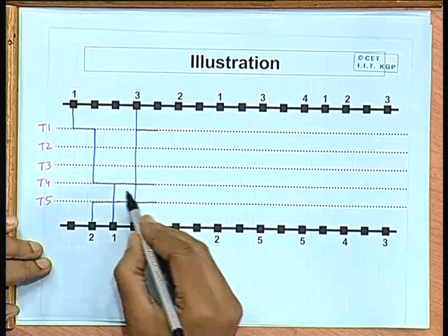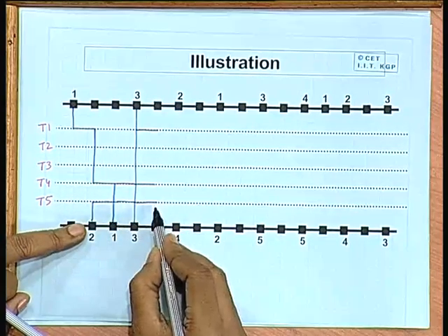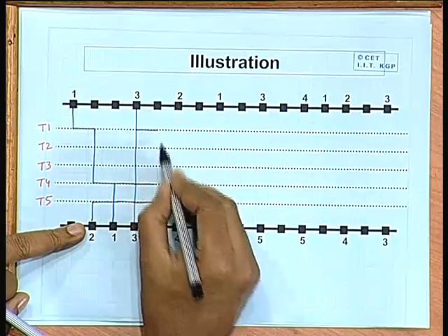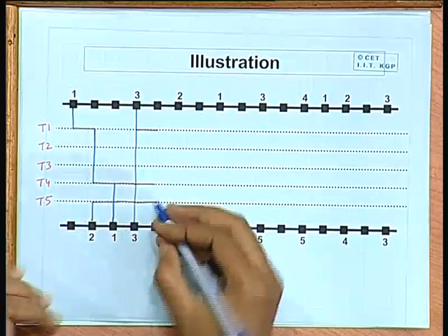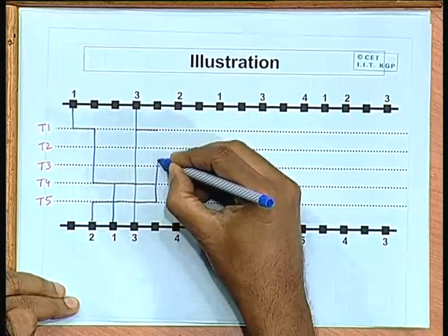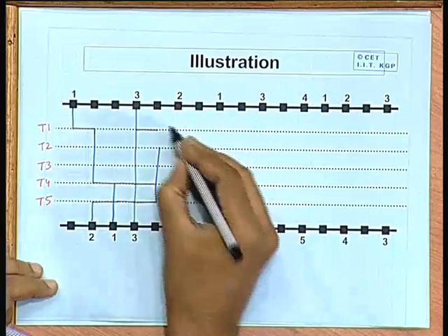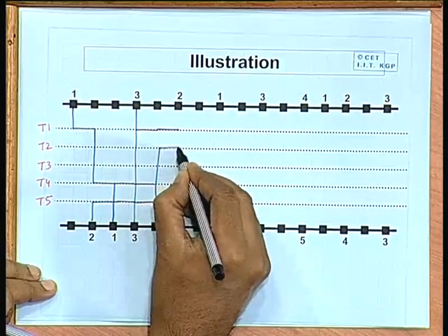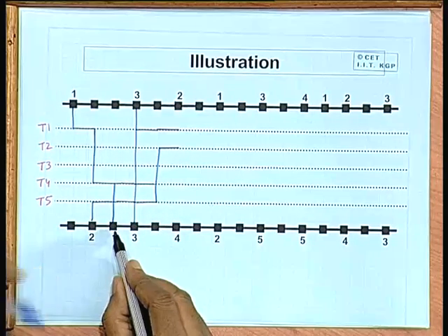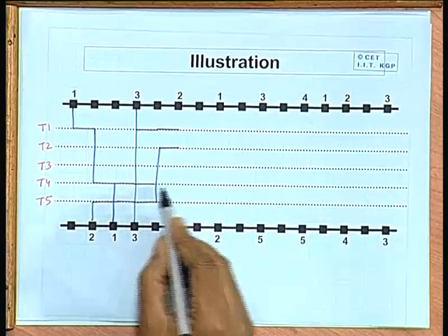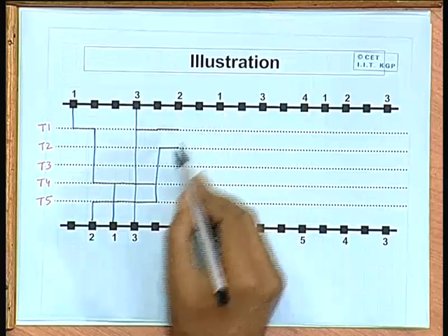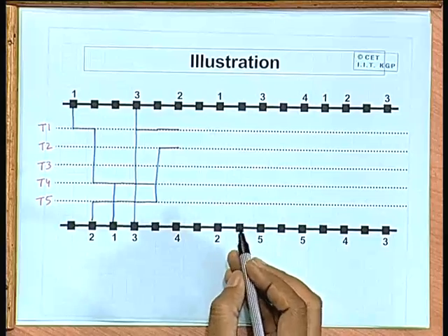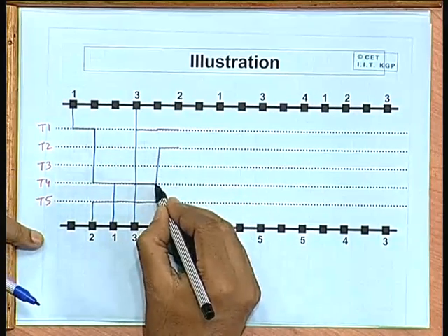Okay. So from here net number 2 you will bring closer to this 2 as far as possible. Now, since already this is occupied, you can bring it to the second track. So net number 2 you can bring up to the second track. Net number 3 you extend, this also you extend. Net number 1, okay, this also has a terminal on the top, this also you, okay, this you cannot do a jog right now, you have already made it, you extend it right now like